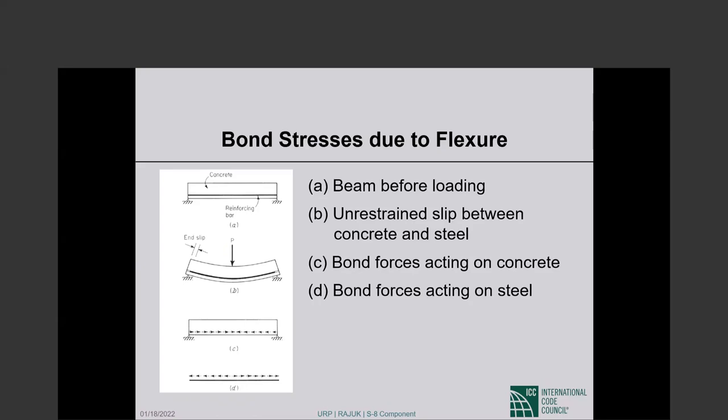The reason why in a typical reinforced concrete beam the concrete and the reinforcement deform together is the bond stresses between the concrete and the steel. Bond stresses acting on the concrete are shown in the picture. They are trying to bring the beam in towards the central load, and that's what the arrows indicate. This direction of the bond stresses is important.